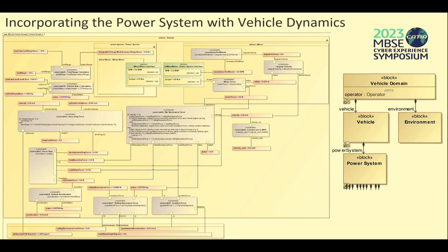So then we have torque coming out that turns those wheel motors. And then we have a few different equations down here, such as our aero drag forces and our net resistance forces. And then there's this constraint here that's an equation that simply sums up all of those forces. Some are negative; I think all of the ones that we've modeled in this case act in a negative way, which causes this vehicle to slow down. So we have aerodynamic drag, the resistance forces, road slope forces, and net linear forces. That all gives us that, and then we put that into the F equals ma equation to determine how fast